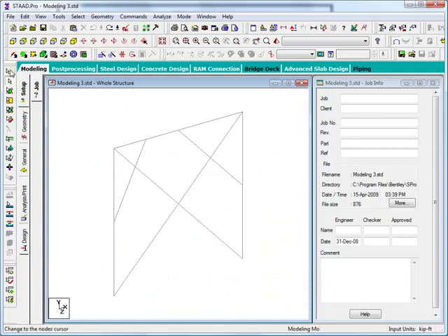Some other reasons why the cursors are convenient as individual function cursors is if you get into a situation where you're working in tight quarters and it becomes difficult to select a beam without getting a node or an adjacent plate. So you can use the appropriate cursor to get only the entities that you want to work with currently.